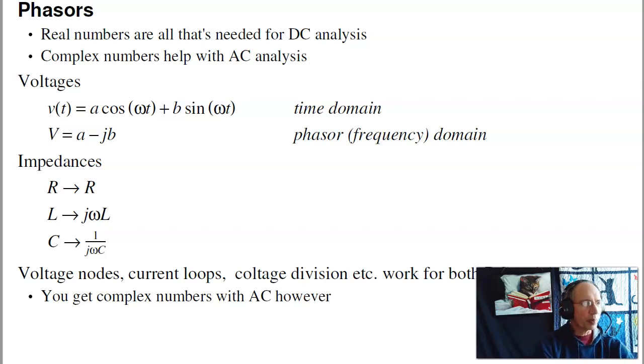Now, what we've been looking at in the previous lecture for the DC to DC converters is trying to calculate the ripple at the output. And in order to do that, I had to take a square wave and approximate it with a sine wave. There's a better, more accurate way to do it. That's Fourier Transforms. If you want a really accurate answer, use Fourier Transforms. It's a lot of work, but you'll get the actual answer. The other alternative is do what we did in the last lecture, make an approximation, and then use CircuitLab to fine-tune it. Now, the Fourier Transforms, that's using the concepts of superposition and phasors.